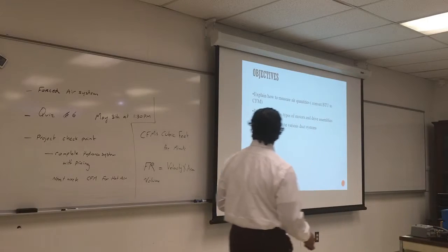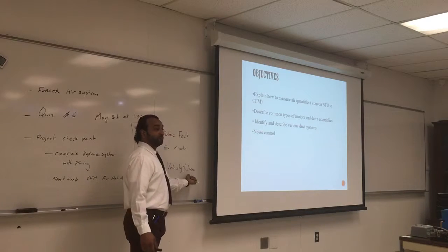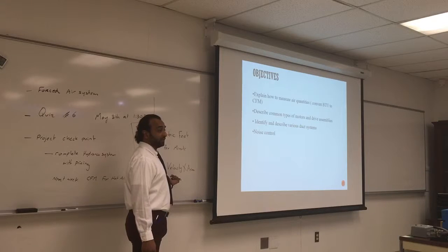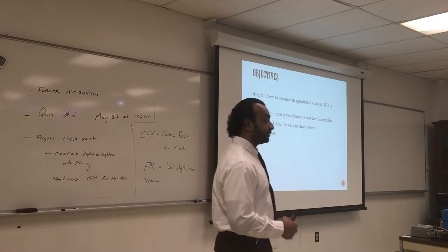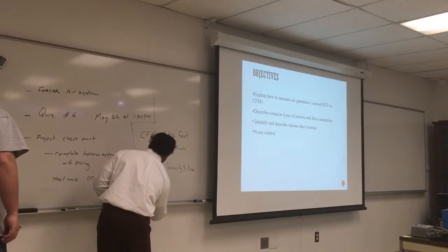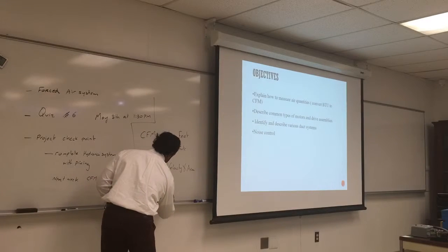So we'll talk about noise control in terms of flow rate and how we change the area to maintain the flow rate. Usually the velocity is more difficult to control, but it is possible to lower the velocity if you have a very small area. But at the end you want to control the same flow rate, volume, which is CFM. You want to keep this constant.